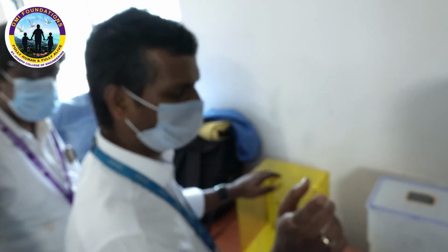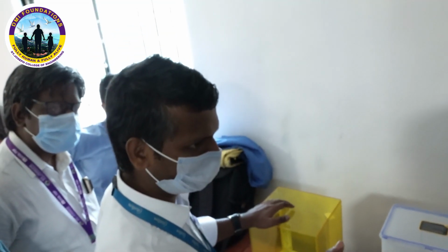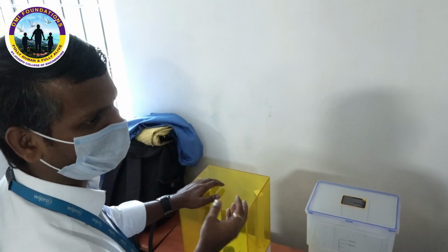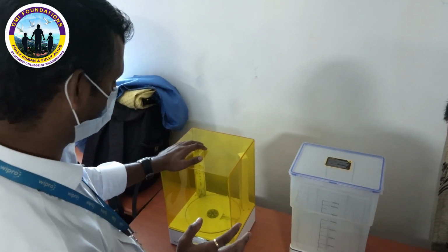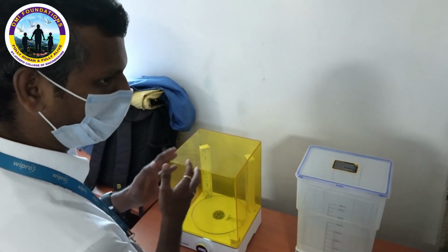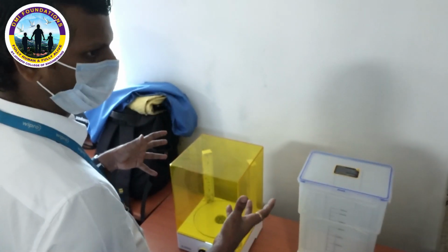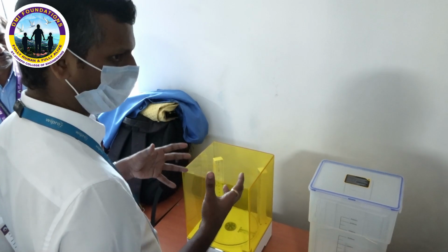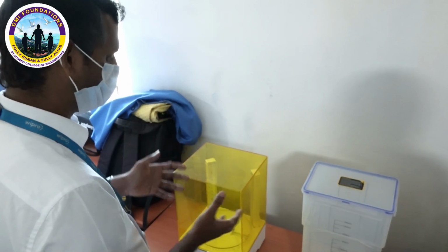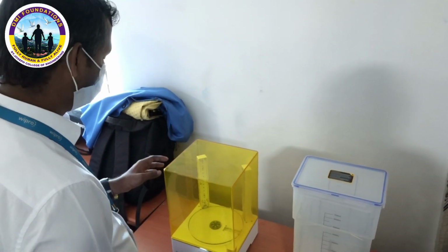Okay, I'll tell you one logic. If it is taking 60 seconds to completely cure, here also you can keep a similar kind of time. Maximum 5 or 10 minutes you can keep, so that the complete part will be cured. If you are making a very big, completely solid component, then you can increase the time. Okay.